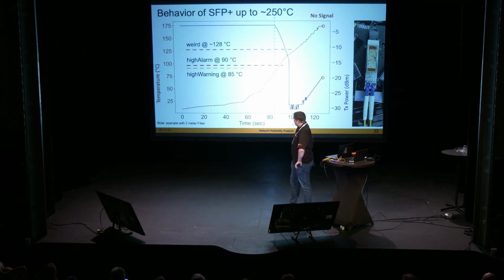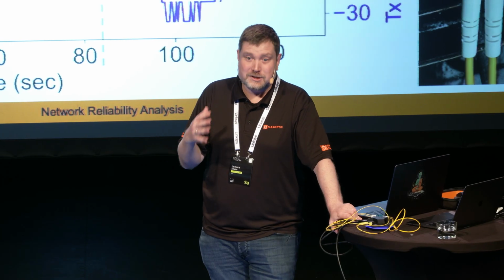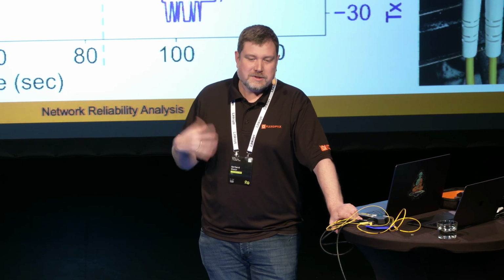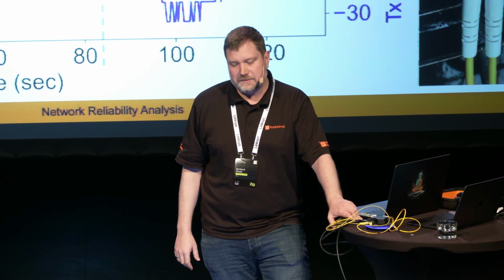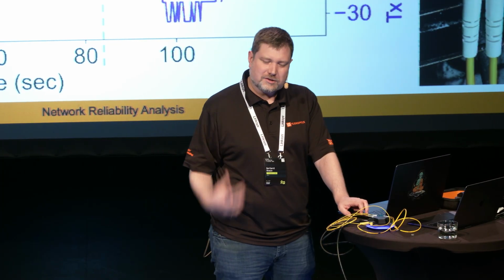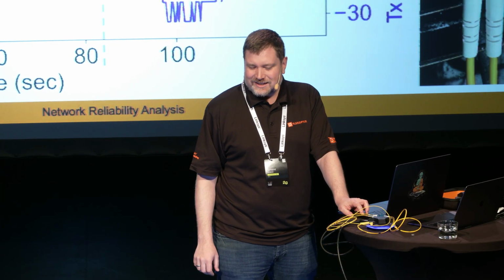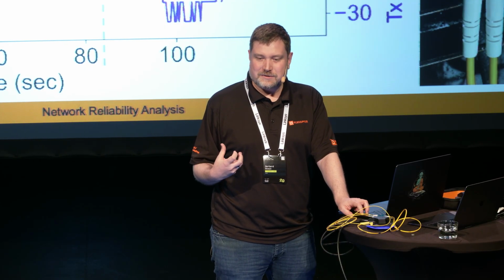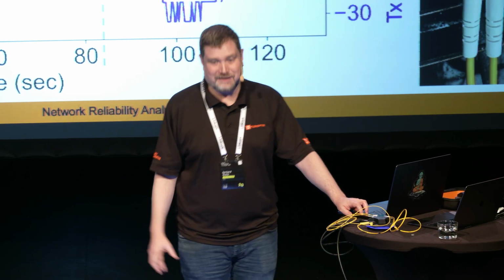So we were not satisfied. We tried another transceiver. Since 120 it survived. We really wanted to see the extreme. So how far can we get? And we tried another experiment with 250, a smaller transceiver, but you can also read out some values just out of curiosity. And it's interesting to observe, if you read out the memory, there's this 128. I just called it weird because, yeah, what does it mean?